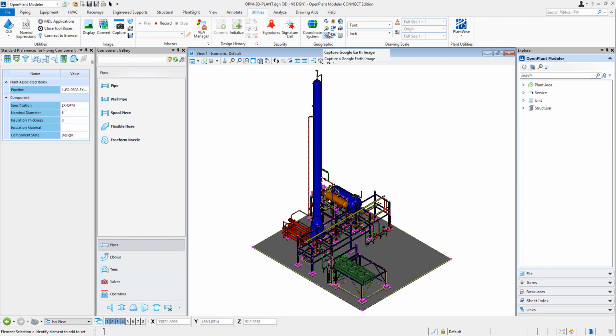So a place mark is a cell that consists of text fields: name, longitude, latitude, altitude. The longitude, latitude, and altitude fields specify the geographic position relative to a datum. For example, a WGS 84 datum, known as World Geodetic System, which is the datum reported by GPS devices and also used by Google Earth. The corresponding position in the design file is specified by the placement point of the cell.